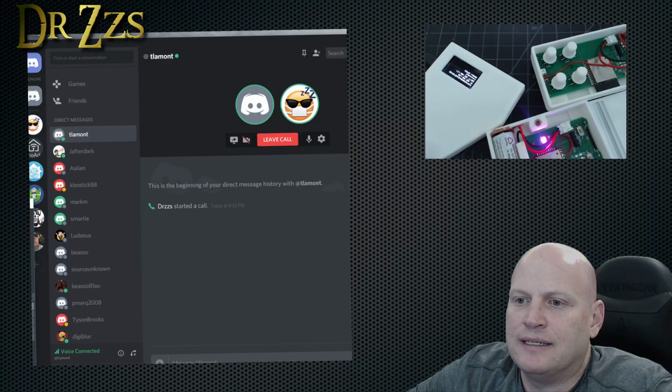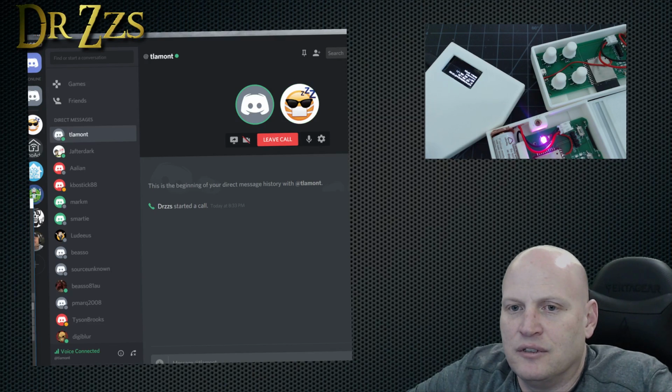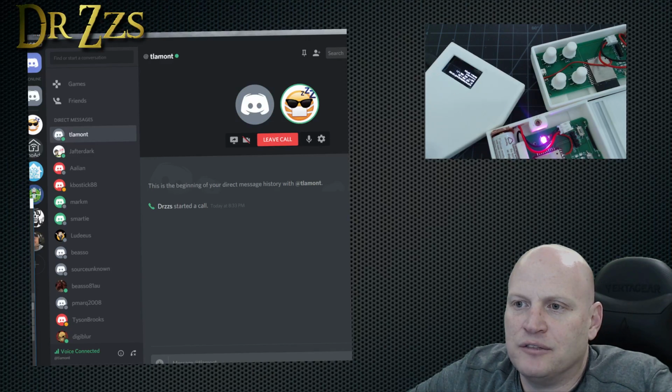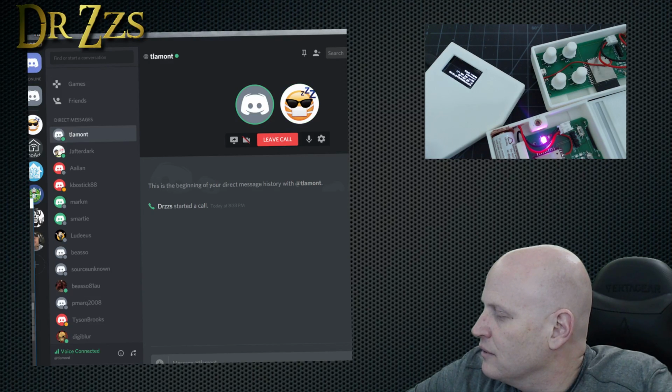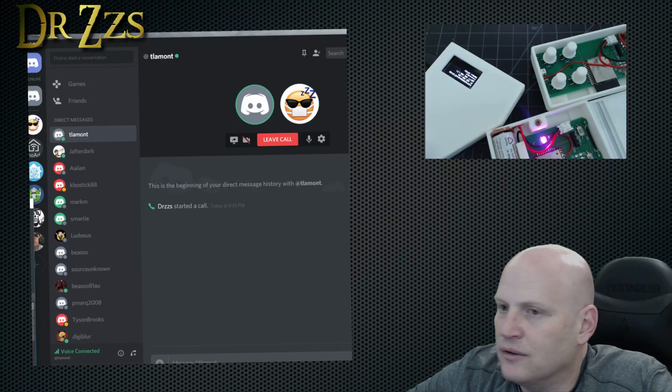Whereas if you're using just plain Wi-Fi, when you press the button, the receiver has to get an IP address, and then send the packet, and that can take anywhere from a few seconds. So the speed, you don't have to wait for it to travel to deal with the router and such. With ESP-NOW, what the receiver does is it listens for both. It is connected to your Wi-Fi network, and it also listens for our access point.